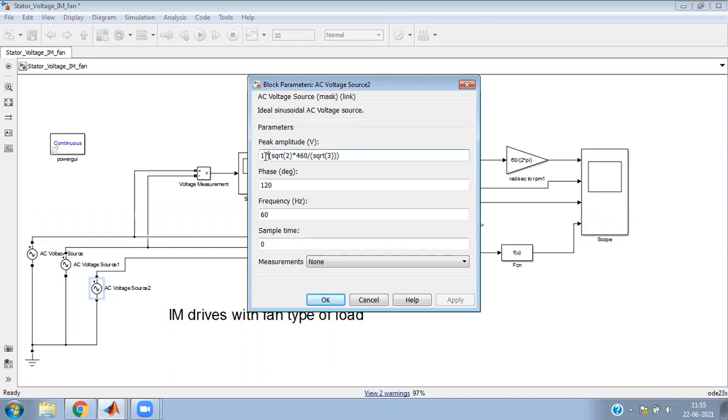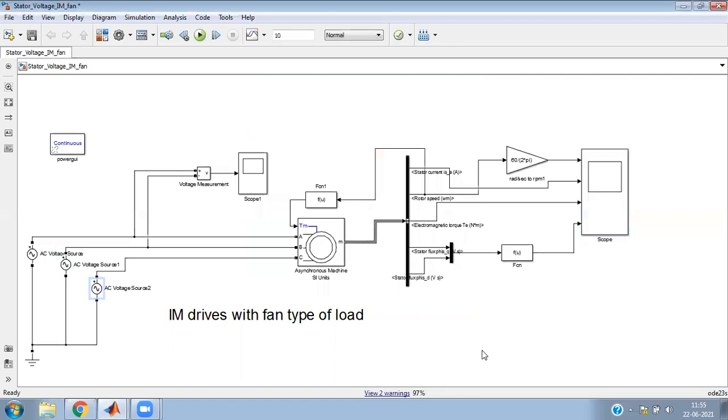As a result of which the motor developed torque will reduce, the speed will reduce, and load torque will also reduce. So whether this motor is running in equilibrium or at steady speed or not, that is what we would like to see. Right? So we have saved this new value and are simulating the 80% of the rated.